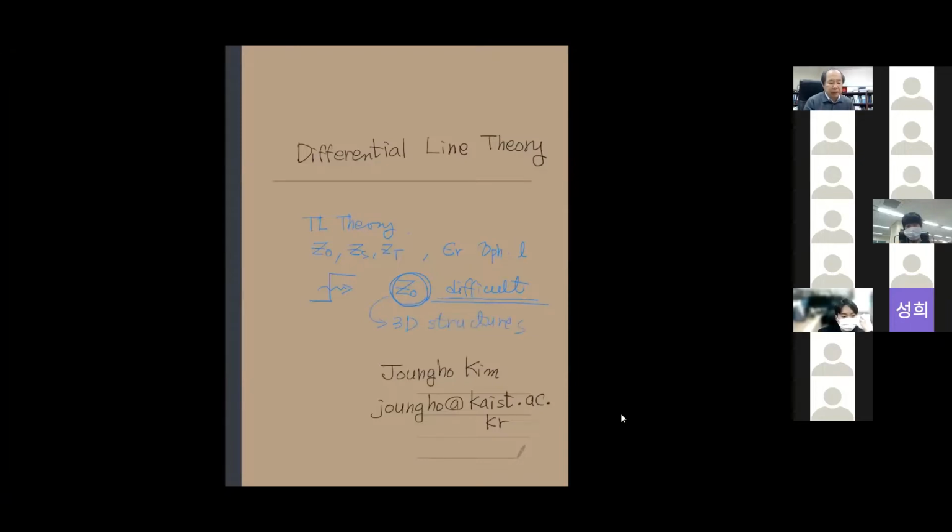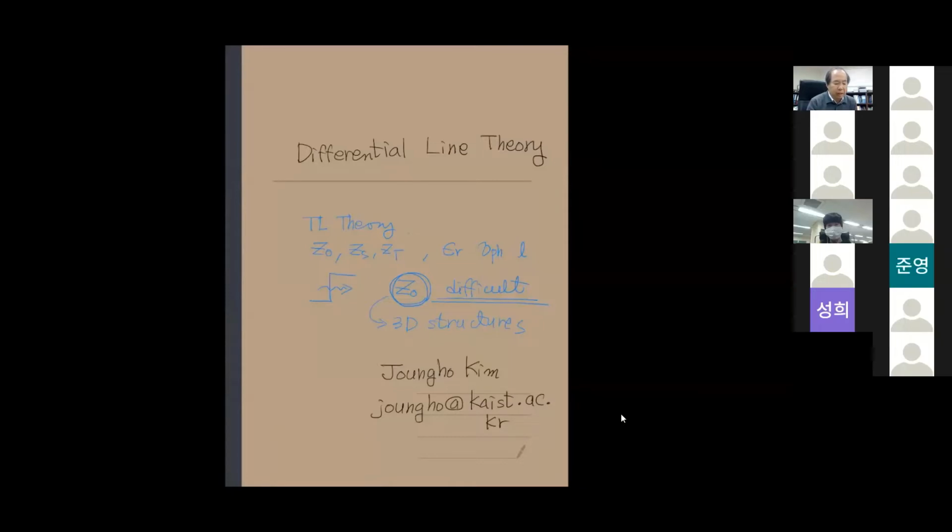Sometimes our transmitter and receivers are on the same plane inside the chip, but in a lot of cases, we have to send digital signals from chip to chip. Then it has to go through from chip to package, PCB, and sometimes we have to go through cables. Because of that, impedance in three-dimensional structures such as package, PCB, and connector, and cables, all these have three-dimensional structures, and it is very difficult to maintain constant impedance.